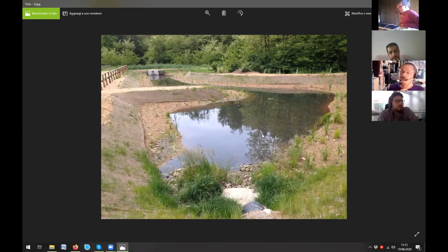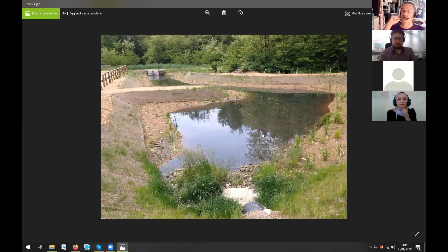I personally suggest always to oversize the manholes for checking and inspections, because most of the time the problem of any drainage system is that it gets polluted and used as a dump site, so you might have the perfect one which is not properly working. Those help you sometimes to overcome the problem, if you can afford it.